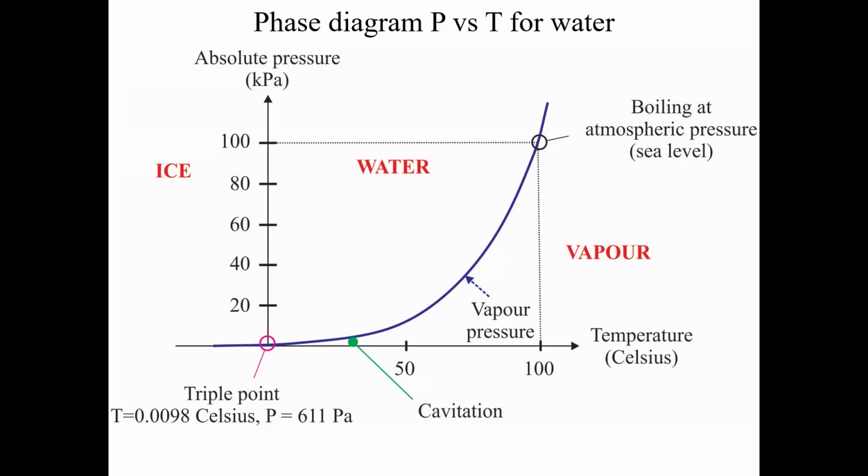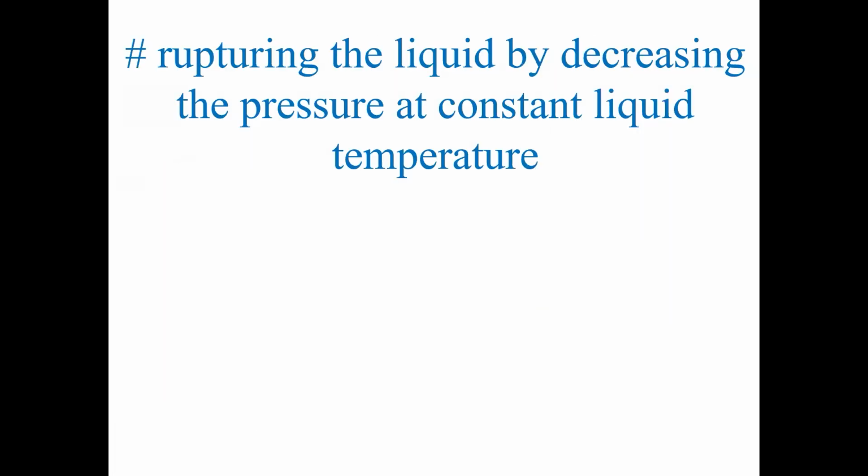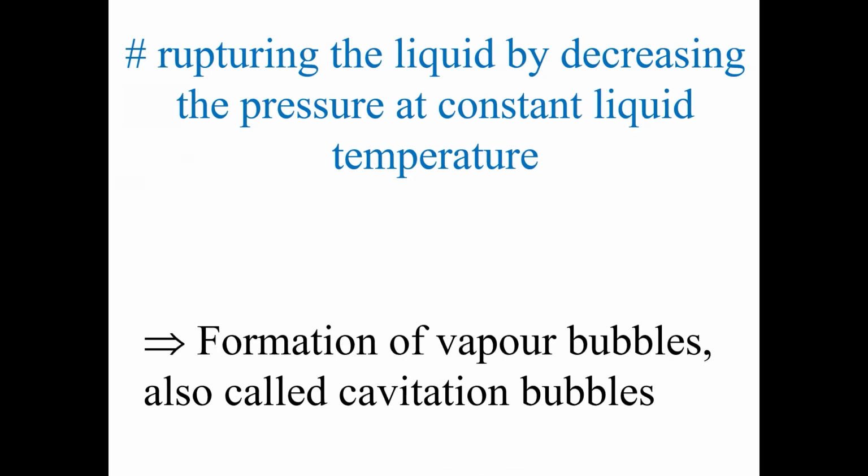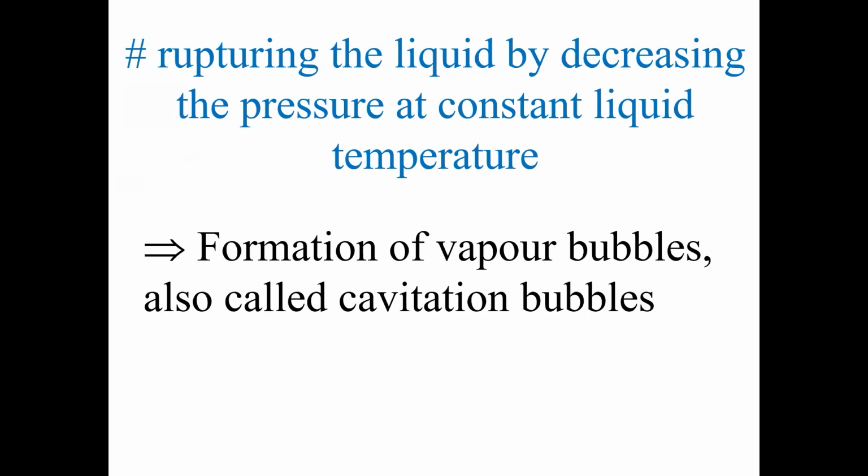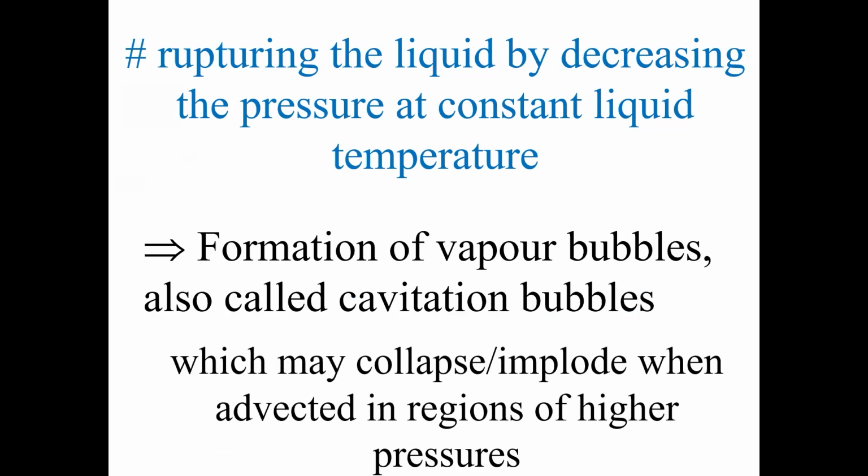Considering some water at ambient pressure, a sudden drop in pressure would lead to cavitation. It is basically the rupture of the liquid by decreasing the pressure at a constant temperature, leading to the formation of vapor bubbles, also called cavitation bubbles, which may collapse and implode when advected in regions of higher pressures.